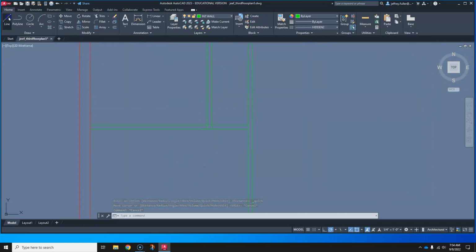Okay, so I'm going to click on the line tool, and again I'm going to activate this reference point down here at this corner next to where my cursor is. I'm going to activate it, so I'm going to hover over it. I'm not going to click on it. I'm going to hover. I'm going to get that little X or that box to come up, and then I'm going to go upwards. Okay, I'm going to go up 1 foot. So I'm just going to take 1 foot of that bedroom space. I'll type in 1 foot, and boom, my line starts at that 1 foot point.